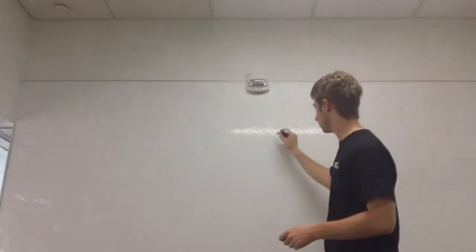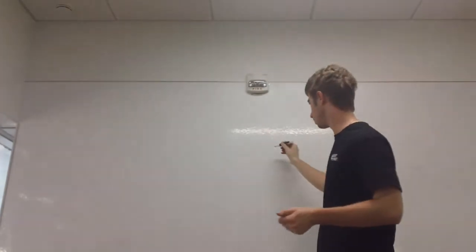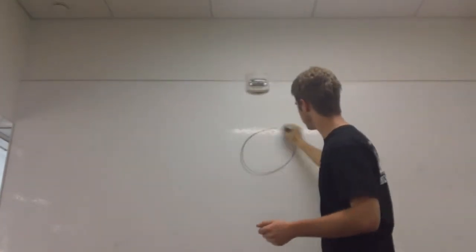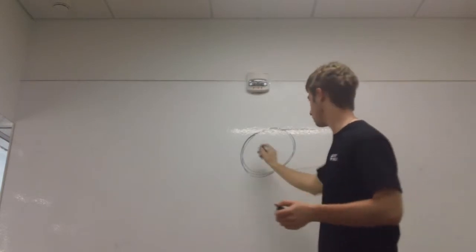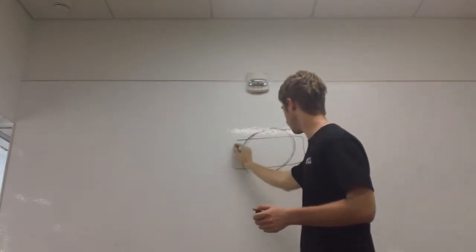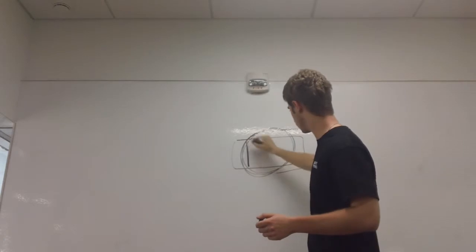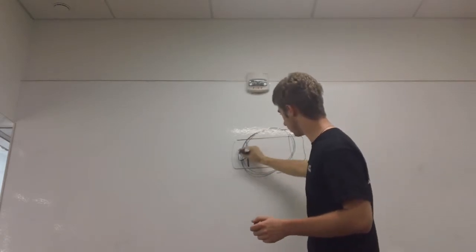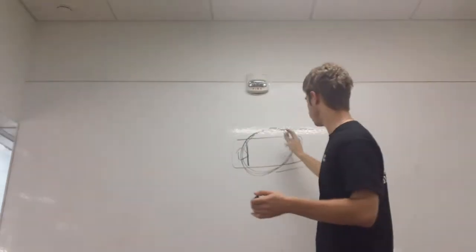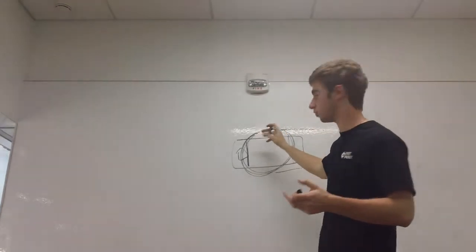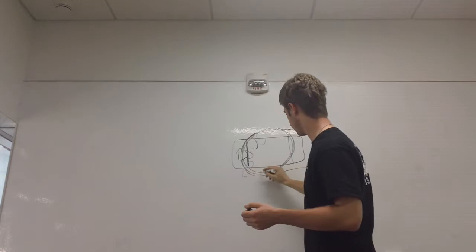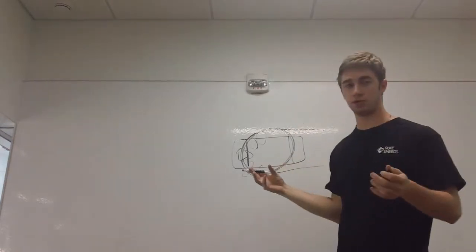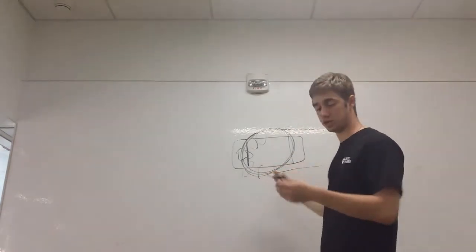Okay? So an induction loop sensor works by measuring the inductance at different times. And when your car is over top of this loop, the axles and the engine and all these metal parts will disrupt the magnetic field produced by this inductor. Okay? So we know inductors produce magnetic fields, and when it's disrupted or altered, the inductance is going to change.